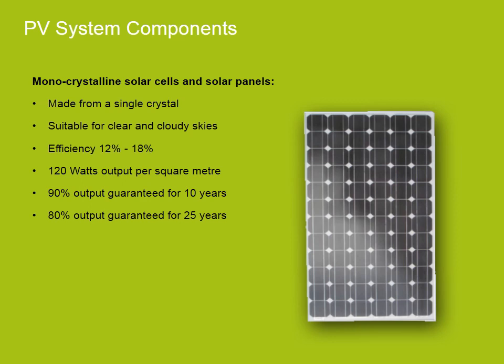Monocrystalline silicon cells are generally the most efficient PV cells and produce the smallest size solar cells, meaning they maximize efficiency. Due to higher production costs, monocrystalline cells tend to retail for a higher price than other technologies. Further to this, they don't perform as well as polycrystalline cells or thin films under higher temperatures over 25 degrees Celsius.